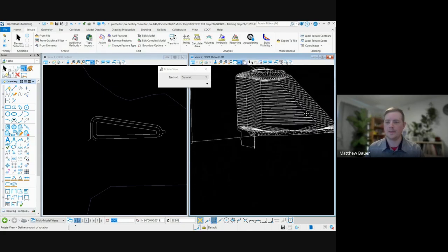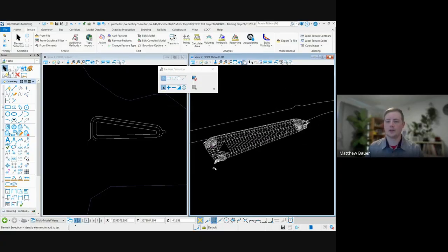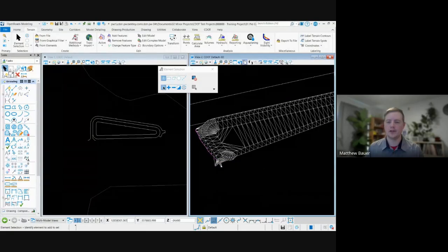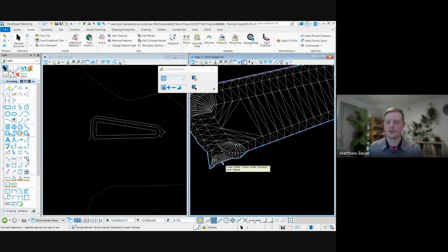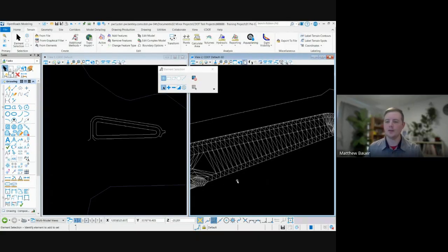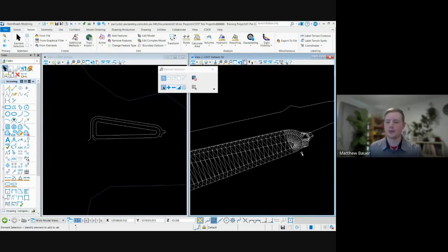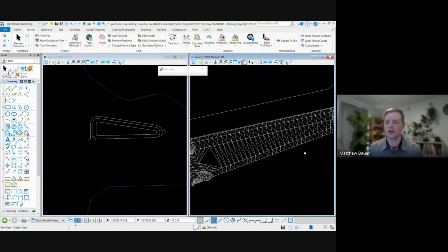it shows up as a 3D surface. So this is its own terrain model. I didn't specify a feature definition, so it probably called it terrain model 1. That's fine for this example. If we reference this into the file that we cut our cross sections from, it'll cut cross sections, it'll show up, and it's a fairly quick and simple way to grade out and show an odd shape here.